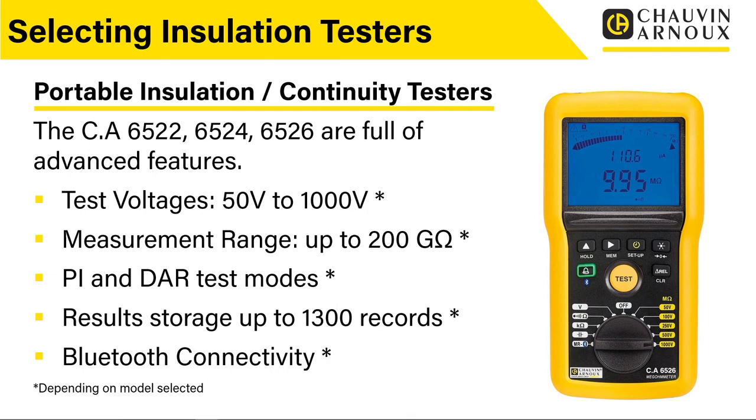So if you're not quite sure, always have a look at the data sheet and you'll be able to pick out exactly which features you want. Within this range of products, we've got test voltages from 50 volts all the way up to 1000 volts, selectable using the rotary knob, as you can see from the image there. Again, measurements up to, in this case, 200 giga ohms. So again, we're talking a really high measurement range on these products.